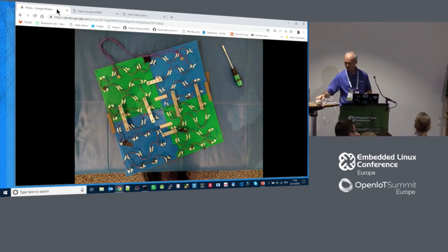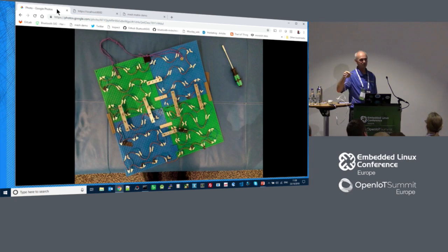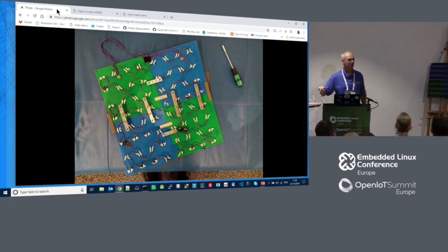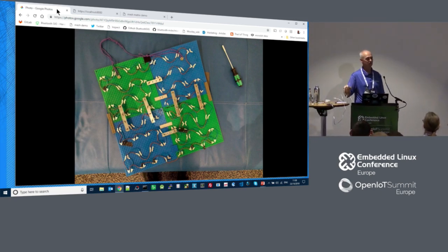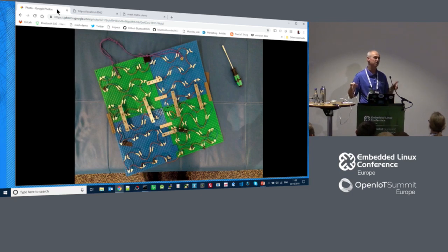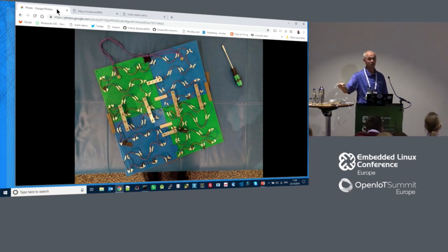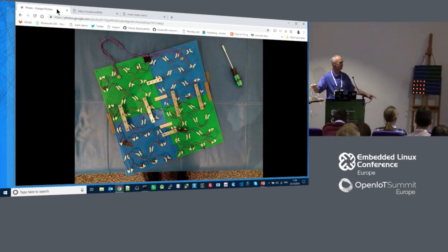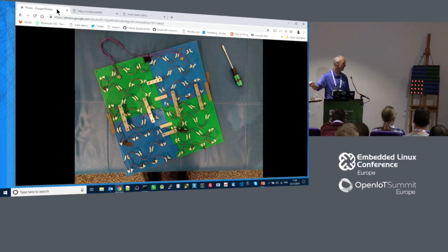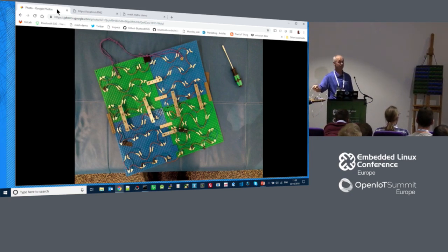Now, node number 65 is this thing here, which is a generic on-off client. It's going to publish to the group address that these guys have subscribed to. And this is kind of the normal case that we're using other microcontroller-based devices to switch things on and off, change the levels, that kind of stuff in a smart building. If I press button A, what do you know, they came on? Because it published to the group address they've subscribed to. If I press button B, what do you know, they switched off? Oh, I feel secretly relieved. But I'll keep that in my head so you don't know.